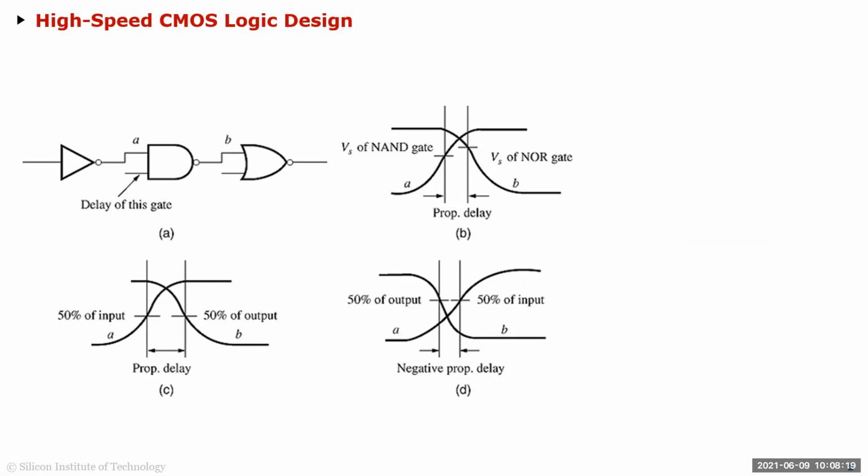So you're going to get all these reports. For example, if you're an STA designer, you're going to get all reports, and typically what you'll be dealing with is what's called the critical path, right? So you have a clock frequency, and you want to drive your circuit with the fastest clock frequency, especially when you're doing high-speed designs, right? And essentially you want to make sure all your delays, from one clock edge to another clock edge, are within that clock cycle. If you are more than that, then obviously you have a problem.